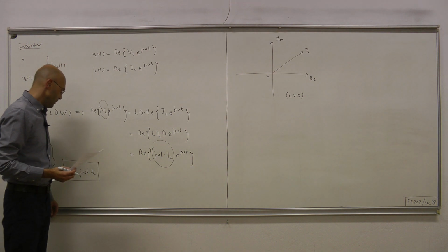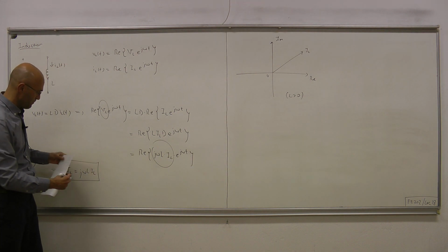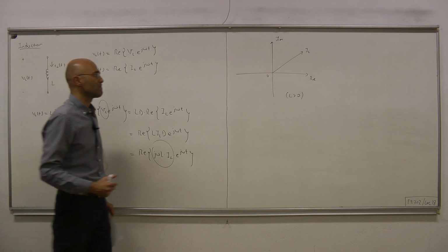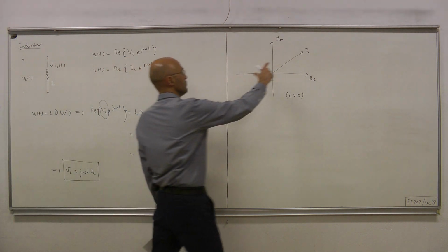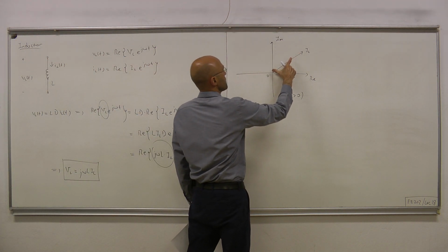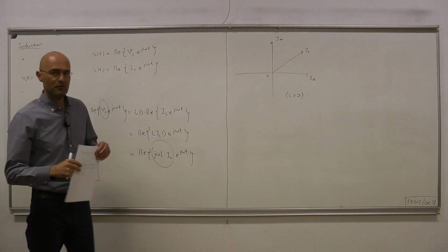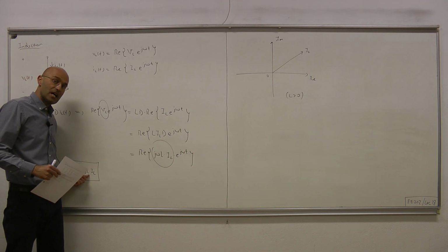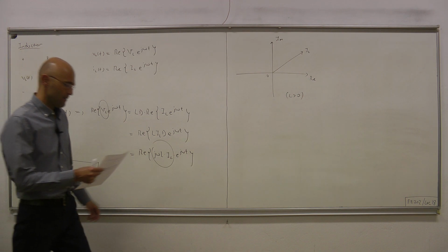Now, if that's IL, then the magnitude of VL is omega L times the magnitude of IL, okay? Depending on whether omega L is smaller than or larger than 1, VL will have either a smaller magnitude or larger magnitude, and the ratio of the magnitudes will depend not only on inductance but also on the operating frequency, okay?